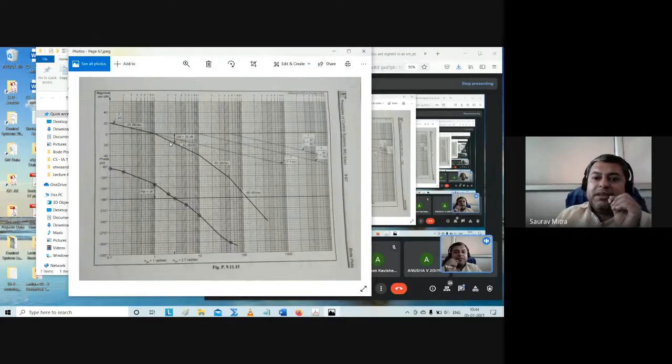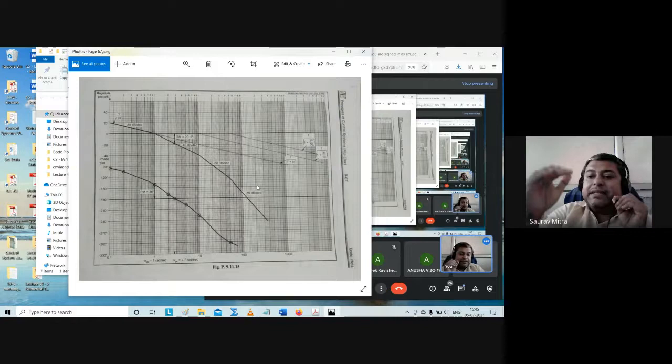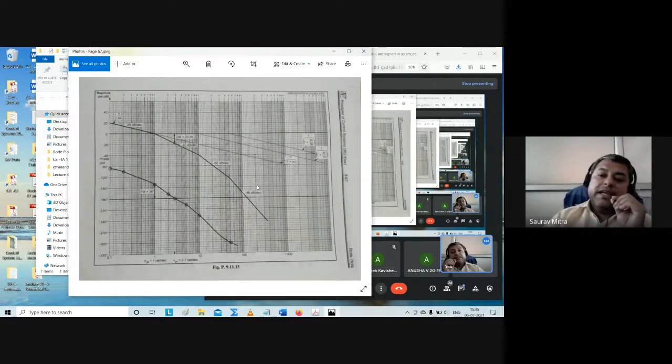So I am finishing this session with this question to you. What should be the value of k, so that you have a gain margin of plus 10? Here you have a very good gain margin, plus 20, but a little less will also work, so plus 10. That means you have to shift this whole resultant graph by 10 dB above, that means add a gain of plus 10 dB. So how much should be the value of k, so that the gain will be 10 dB? This is the question, and that is the answer.